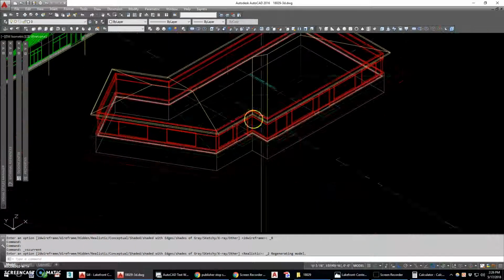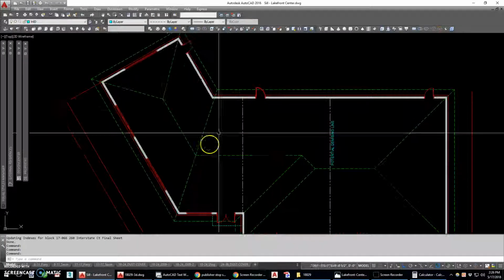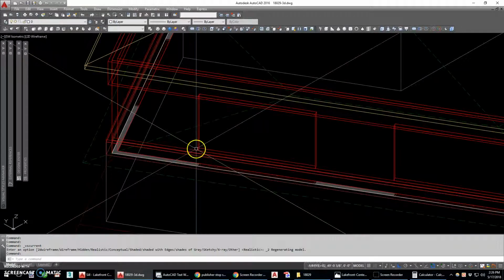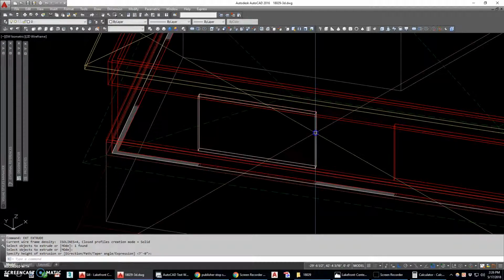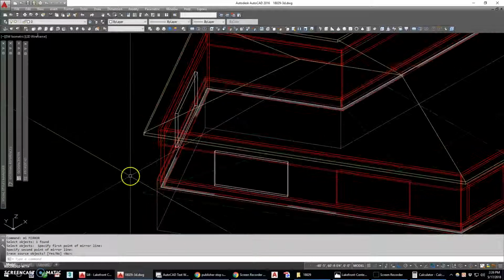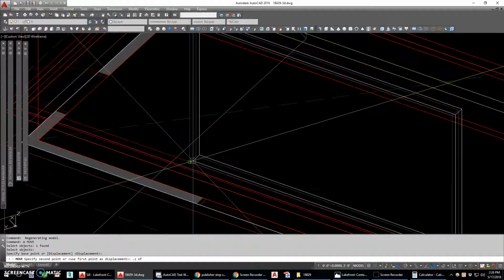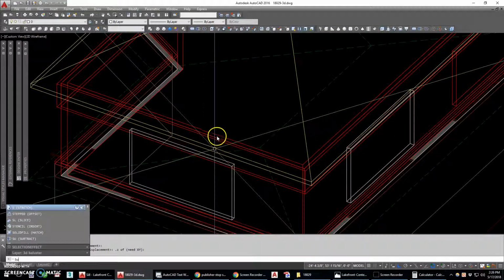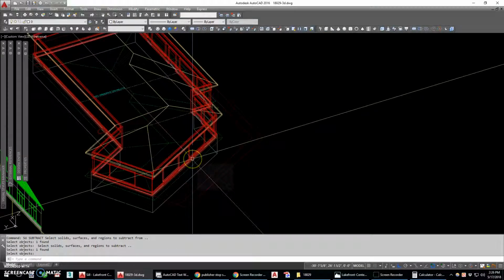I guess I could do, I think there's some windows in the back. I may as well. Nope, just one on that side. Maybe I'll just go ahead and create a new box, extrude that up, and then if I mirror this on the 45, it gives me a window on the correct side, and I just have to move it into position there, and I can subtract it out of my wall. And I've got a window there too.